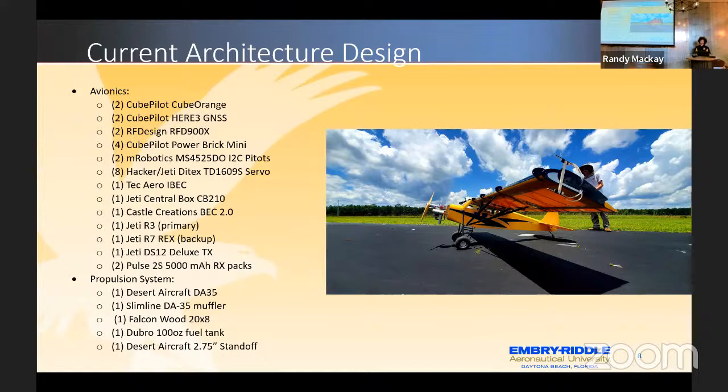convert to quad planes. So phase 2 is the standard airframe. Phase 3 would be essentially doing vertical takeoff and landing testing of the redundant systems. If I were to do that with a large airframe, I'd be at 70 pounds. With this airframe, I can be under 50 pounds if I incorporate vertical takeoff and landing hardware, such as a pair of lift booms under each wing. On that note, the airframe did have some hard points to incorporate lift booms where the struts are, so that was another convenience.